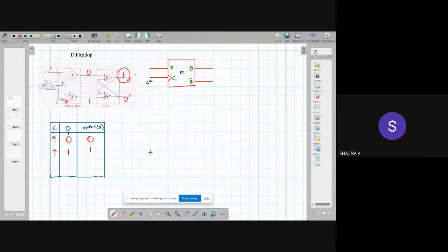Okay. Then now we can see what this D is. Actually, this is called the D flip-flop since this flip-flop produces output same as input, but it will introduce a delay. That is the time interval taken for us to apply the input and obtain the output. There will be some delay between input and output. So this D actually stands for delay. Okay. So D stands for delay. So this is the delay flip-flop, or D flip-flop, meaning it applies just a delay, no other modifications.